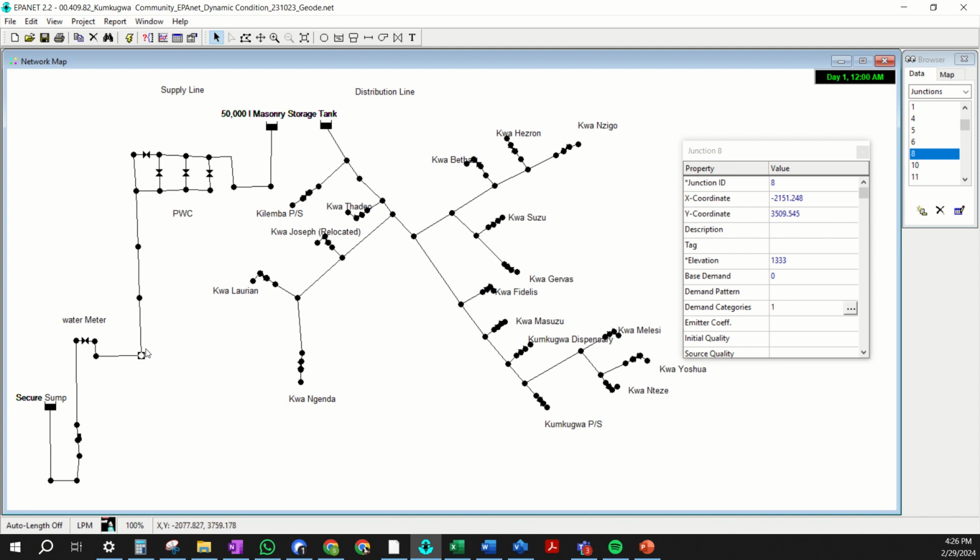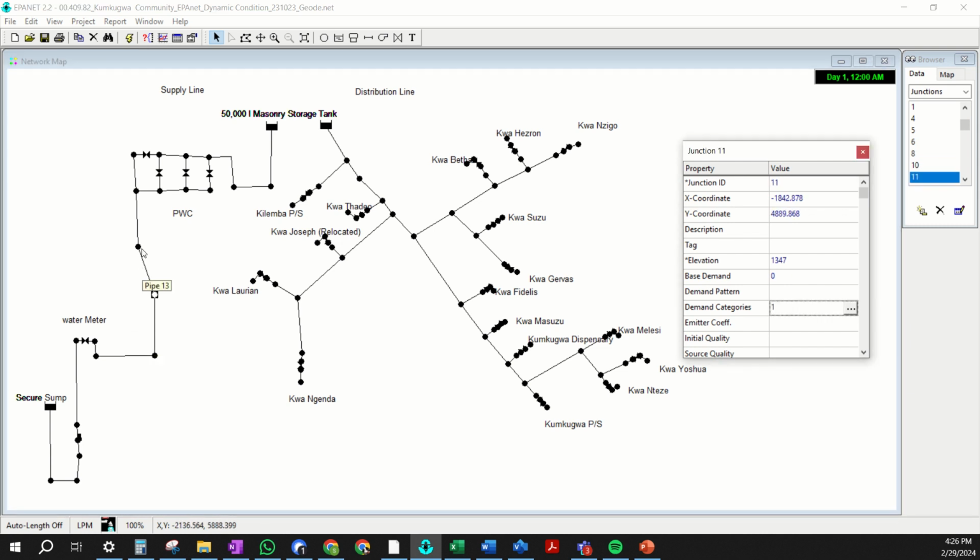And your supply line should resemble the KMZ. It should look like the KMZ so that the reviewer and anyone else looking at this file can understand what they're looking at. And also the length of the segments should resemble the length of pipe.